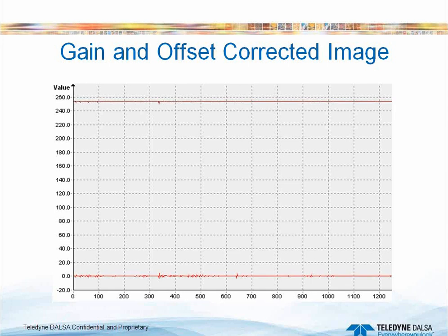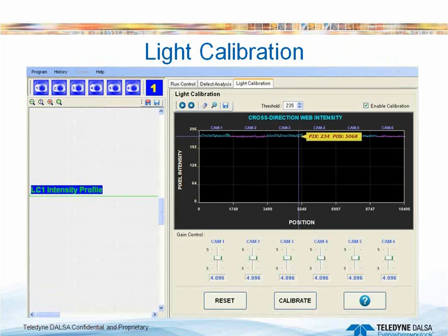Again, this is very difficult to do in a two-dimensional array, because you would have to do it on a per pixel basis, both in X and Y. So here's a utility that was used in an application where you have 6 cameras together, and each one of those cameras was flat fielded to get the most gain, and it's individually programmed. You can tell on the left here there is the line that was used to measure the intensity that's shown on the graph.